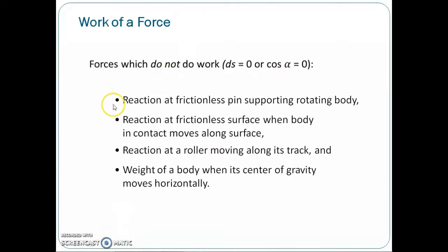These are examples of when forces do no work: the reactions at a frictionless pin supporting rotating bodies, the reactions at a frictionless surface when the body in contact moves along the surface, reactions at a roller moving along its track, and the weight of a body when its center of gravity moves horizontally. That is when cos alpha equals 0, and the rest is ds equals 0.